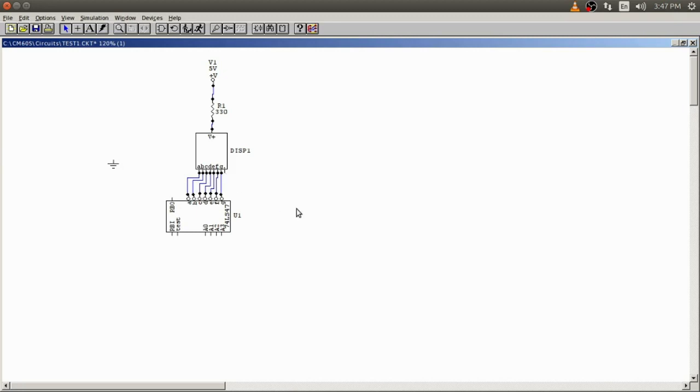So one thing, this IC requires a power supply. However, here there is no power supply pin shown, but we need to have at least one power supply defined in our circuit, where it is already defined. But here, as the property of this one, it is shown that this is connected to something called DVCC, digital VCC, the power supply.